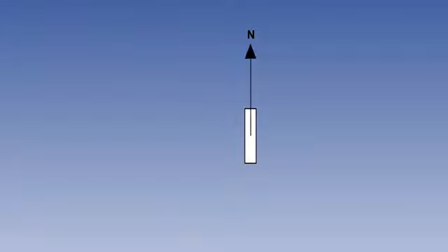We use 2 accelerometers in INS. They are mounted in such a way that one is always kept pointing towards true north. When its accelerations are integrated and processed, we get latitude. The other one is kept pointing true east. When its accelerations are integrated and processed, we get longitude.